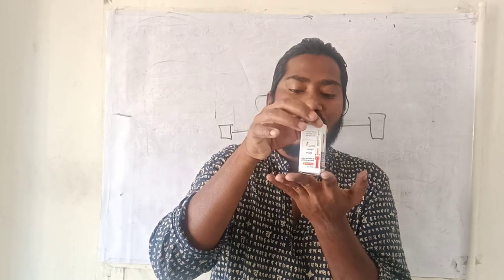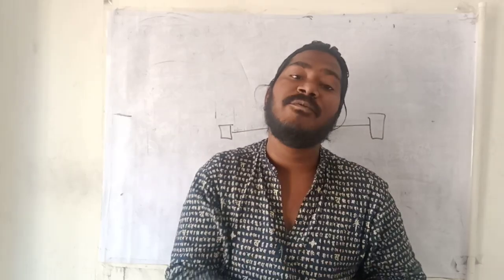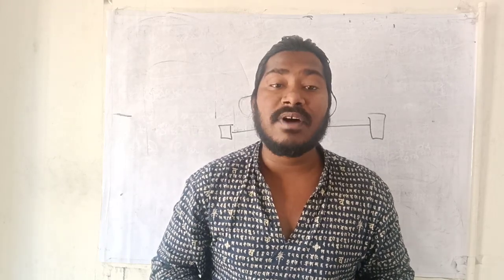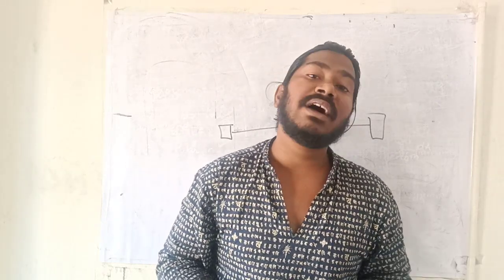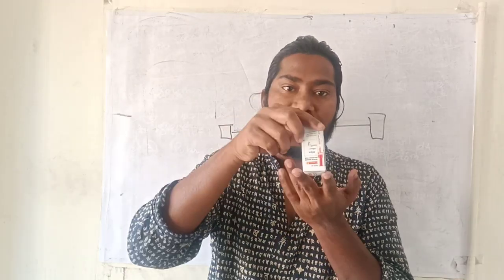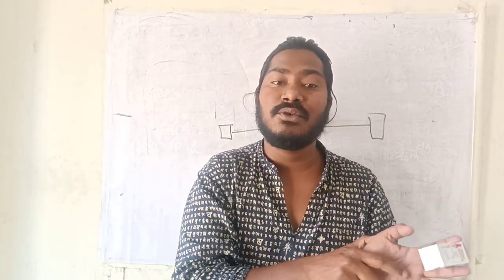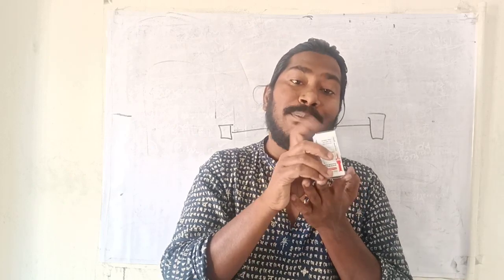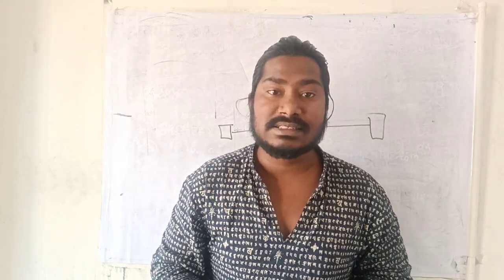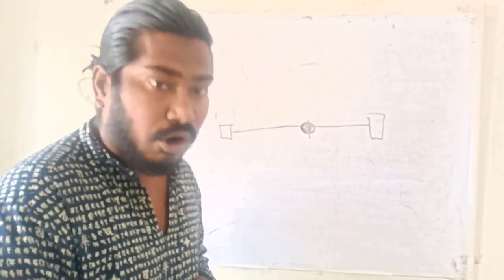See, if I hold it like this and then I start to apply the load, the flex in the material will be very less. With the same dimension, if I use carbon fiber, or on the other side if I use steel, the dimensions are absolutely the same, and the weight of the material that we are using is absolutely the same. But if I change the geometry, your bending, your visible flex, would be very less. Right? So whenever we design a vehicle, we have to consider the area moment of inertia.